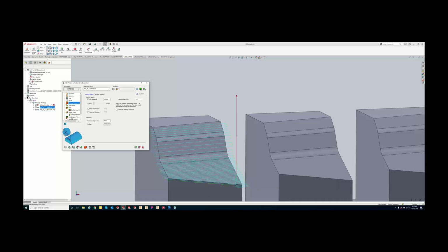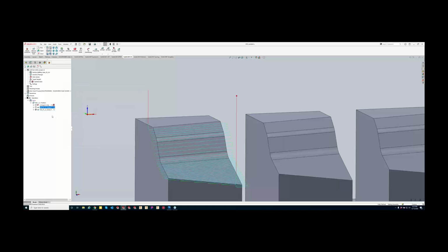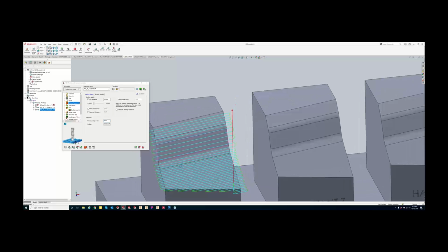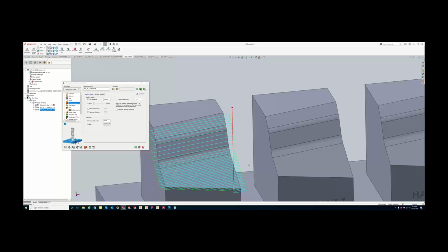We had a 10 thou step over, and one thing I forgot to cover here is the last thing I was telling you guys to do, which is come in here and set your step over. Like we were talking last week, if you set a small step over, you can't see what those lines are doing. So now I have everything nicely spaced out, I can see what that tool path is doing, I've got my gouge check all set, and now I can fine tune the surface we're looking for. And now if we simulate this,